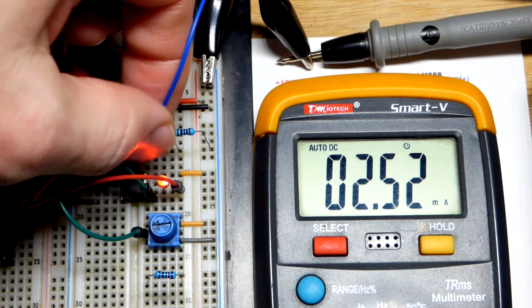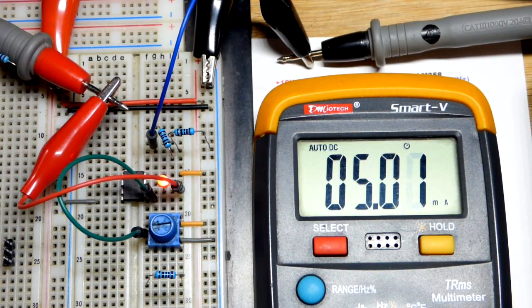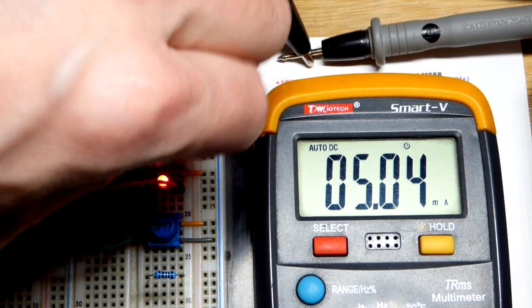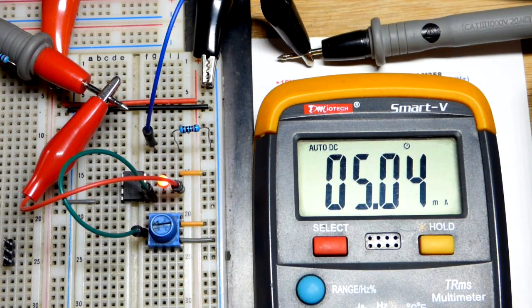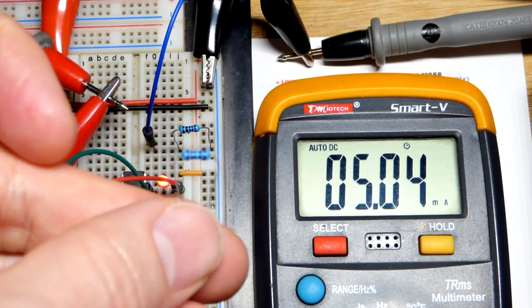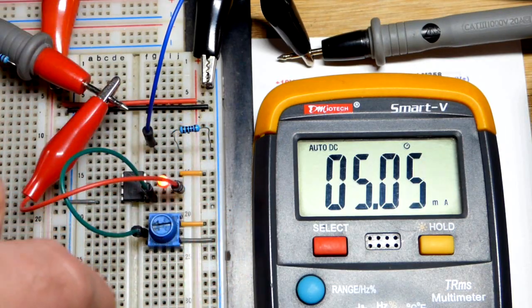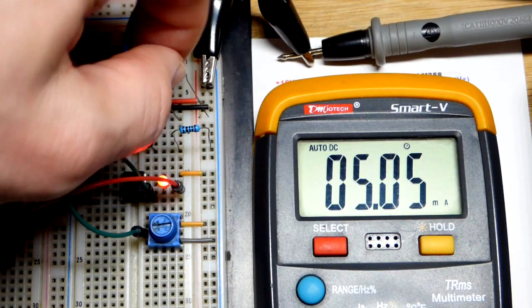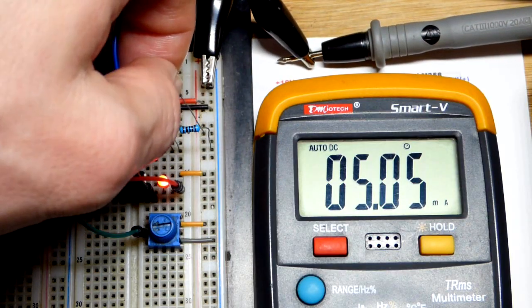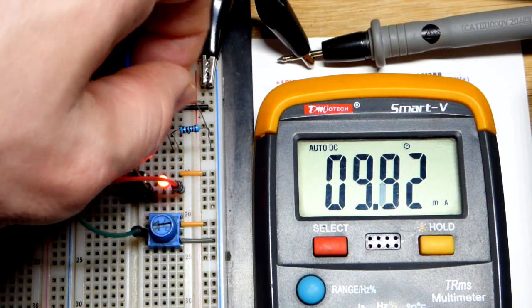Pretty straightforward. And then if I just bypass that one resistor, so we go back to the lone resistor, then we got 5 milliamps of current. Pretty straightforward. So I'm going to pluck that one, and we can also look at 500 ohms. So I do have a 510 ohm resistor. That's close enough. I don't have a 2000 ohm resistor. I have a 2200 ohm resistor. So this is a really easy way to overcome those resistance differences if they're an issue. Just take 1K resistors, put them in series or parallel. So this is parallel.